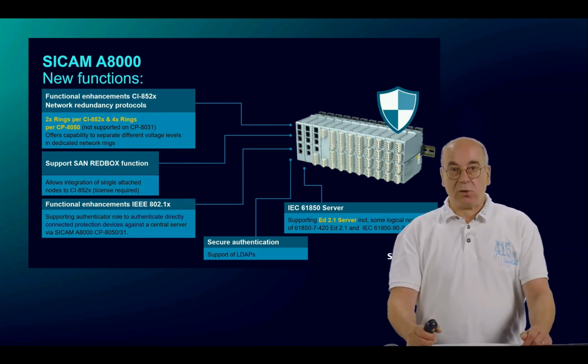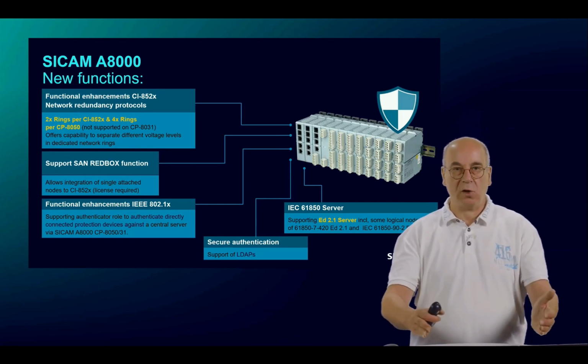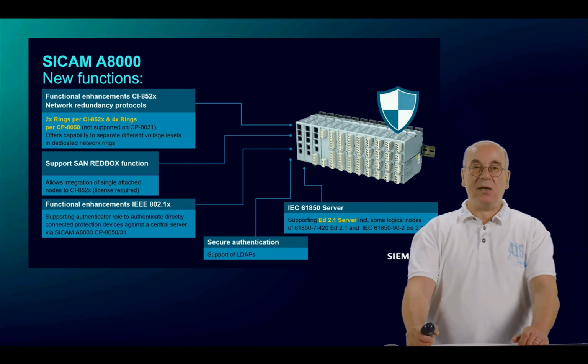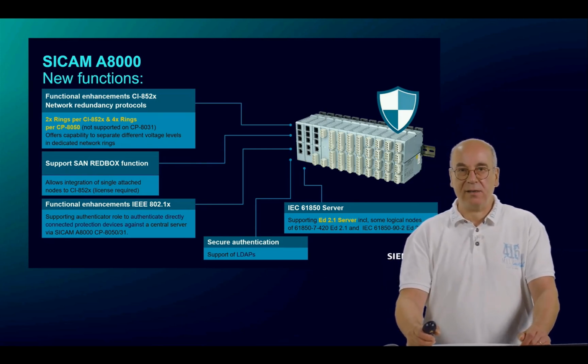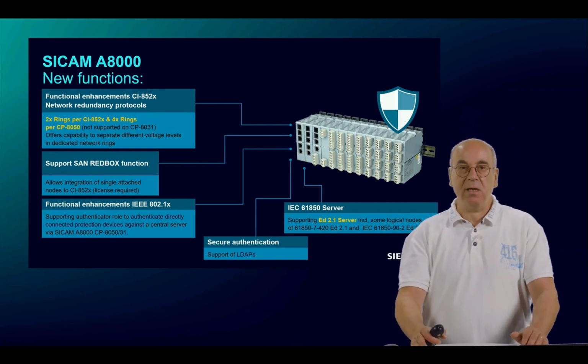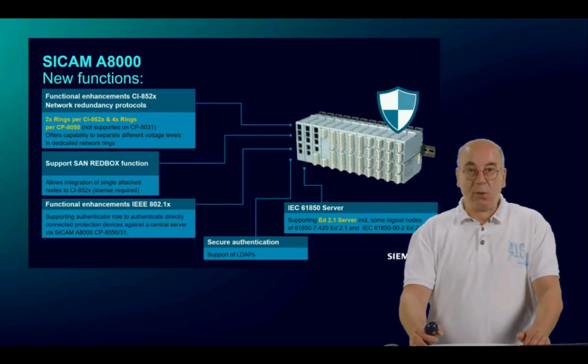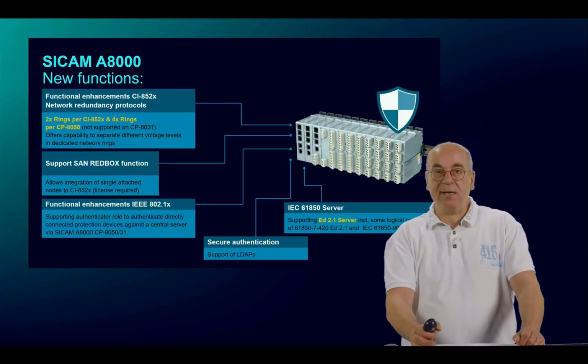For Ethernet-based protocols, different redundancy algorithms are defined in the standard. We know for ring topologies, for example, rapid spanning tree, RSTP, and PRP, ring topology, RSTP and HSR. For networks with star topology, line redundancy, also called dual homing, and PRP.